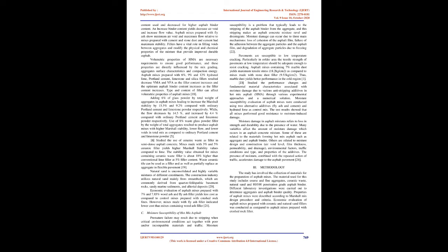2. Literature review. A. General. Flexible asphalt pavement layers consist of mineral filler, coarse and fine aggregates, all cemented by the asphalt binder and blended at pre-specified weight proportions determined from the mix design method. Mineral fillers are fine particles or part of the aggregate skeleton of the pavement which passes the number 200 standard sieve size, that is added or naturally present in the mineral aggregate. 8.